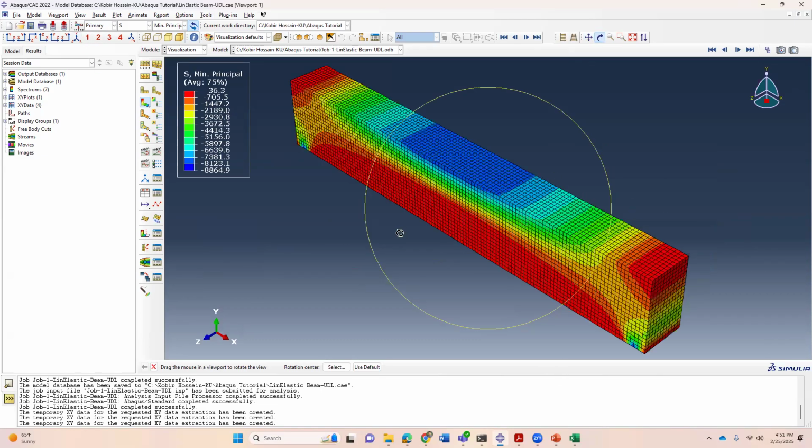I hope this helps. We'll see a second beam with linear elastic plastic material, and as I said, that will be very important to understand the behavior of a steel section. The steel section, as I said, steel is not perfectly elastic, so it's elastic plastic. So under the load, if the beam fails, how is it going to fail?